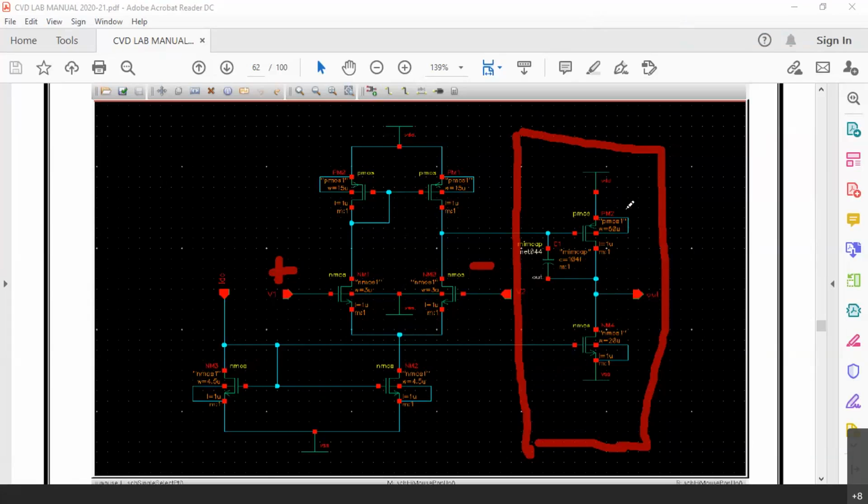Fine. You can see here this PMOS FET, to the gate we are connecting the input and at the drain we are taking the output. As the source is connected to the power supply, the source is AC ground. So here instead of NMOS, a PMOS FET is used as the amplifying transistor, and below we are connecting the NMOS FET as a resistor. This NMOS FET is used in the linear region.